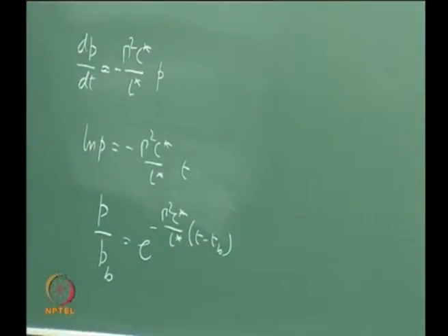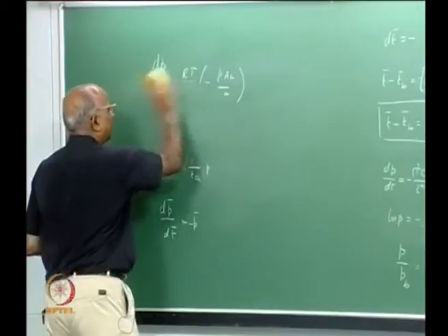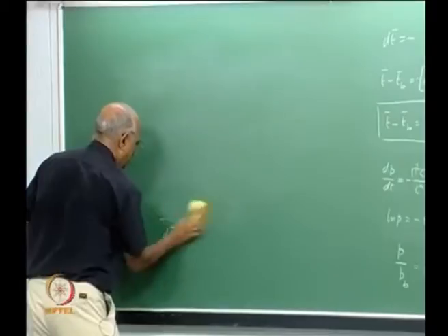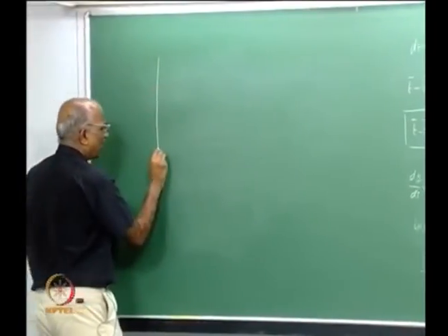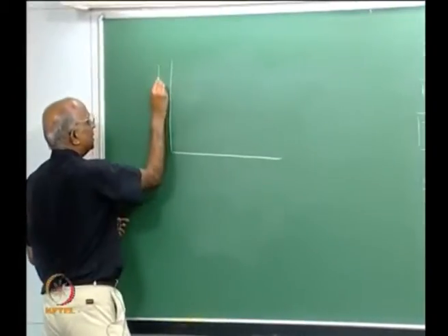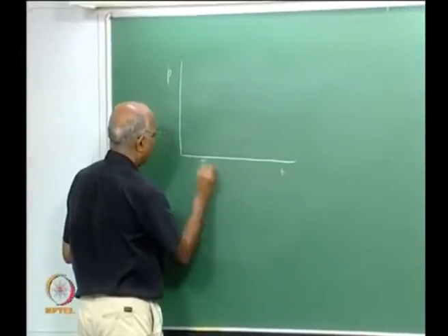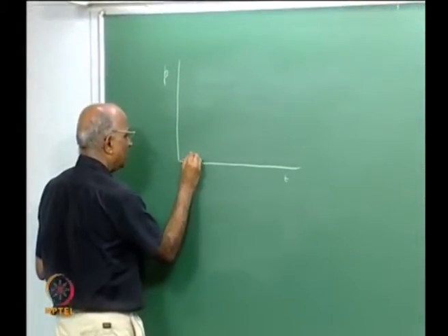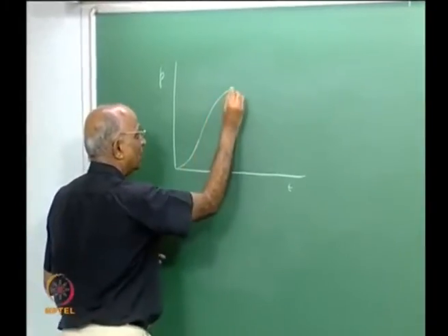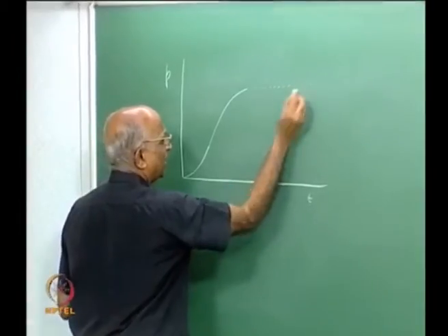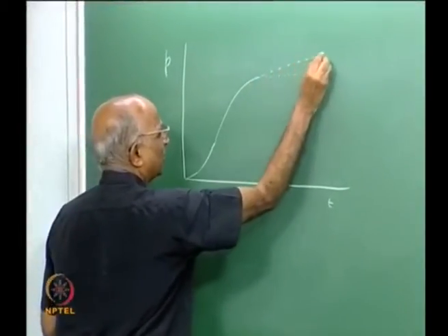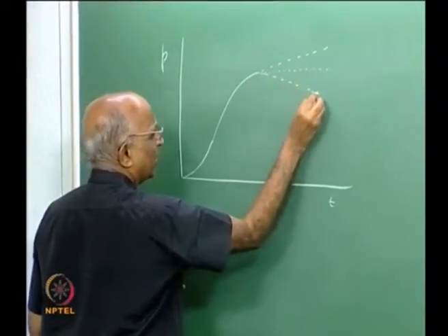Therefore, why are we doing all this? There must be some reason, right? The reason is, what is it we have established? Whenever a rocket motor ignites, the pressure changes with time: it starts slowly, builds up, flame spread goes over here, then reaches, if it is neutral it goes like this, if it is progressive it goes like this, if it is regressive it goes like this.